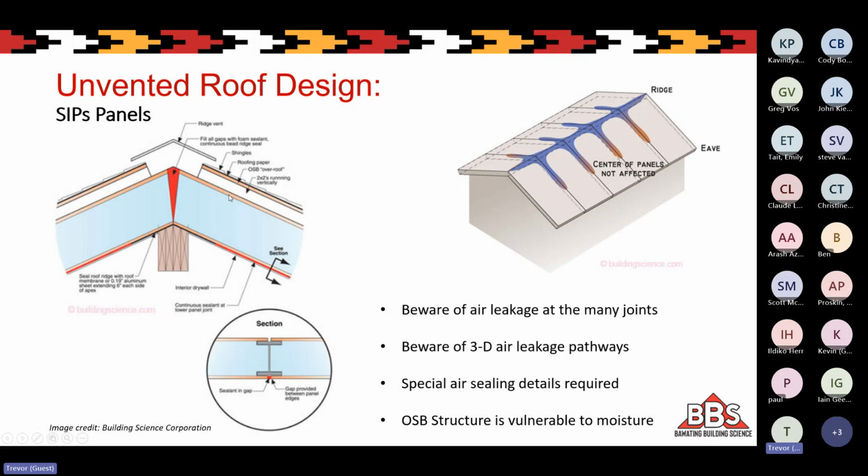And as soon as there's some rot in the OSB skin, you lose your structural integrity, versus a roof made out of 2x10s that can rot out probably 25 to 30% before you have a real structural problem. These can become structural issues really quickly.